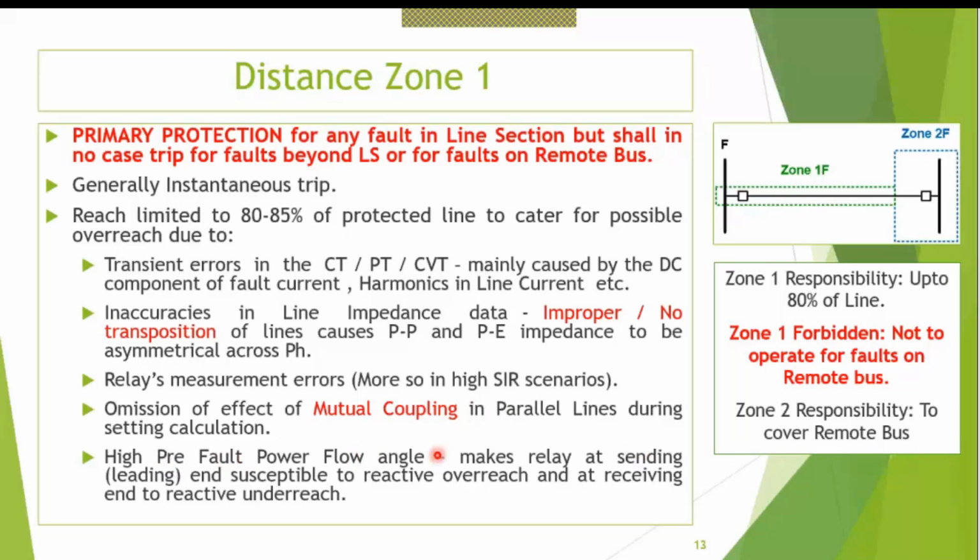High prefault power flow angle makes the relay at the sending end susceptible to reactive overreach and the receiving end susceptible to reactive underreach. This one I have a slide on, later on we'll try to cover it. It's a little complicated.